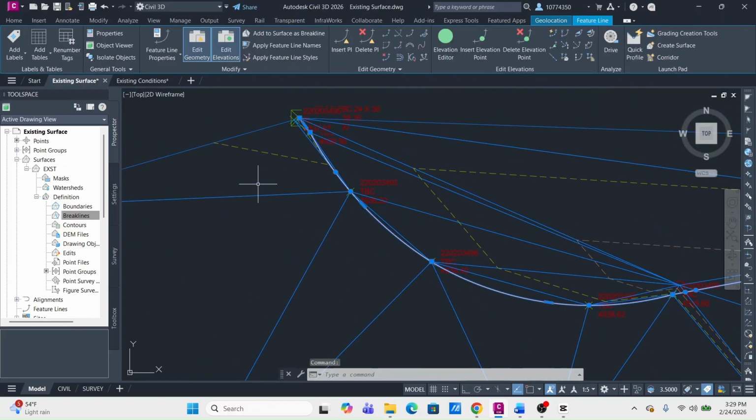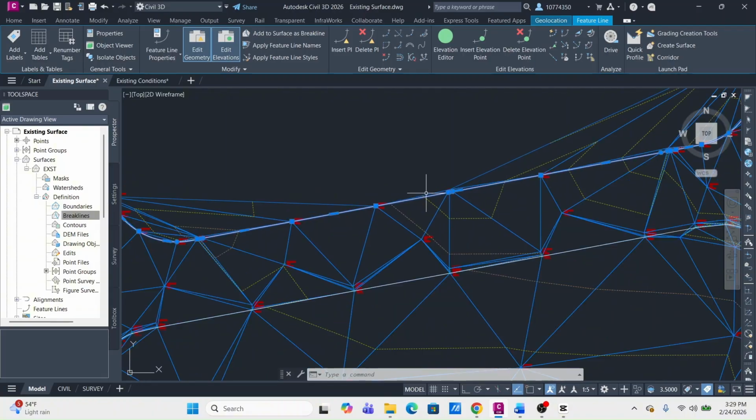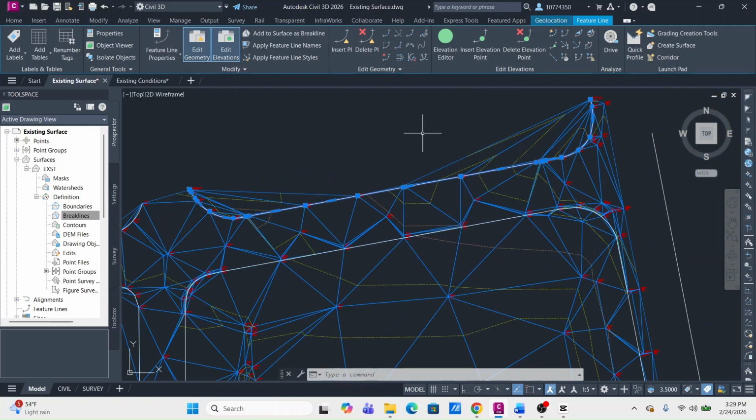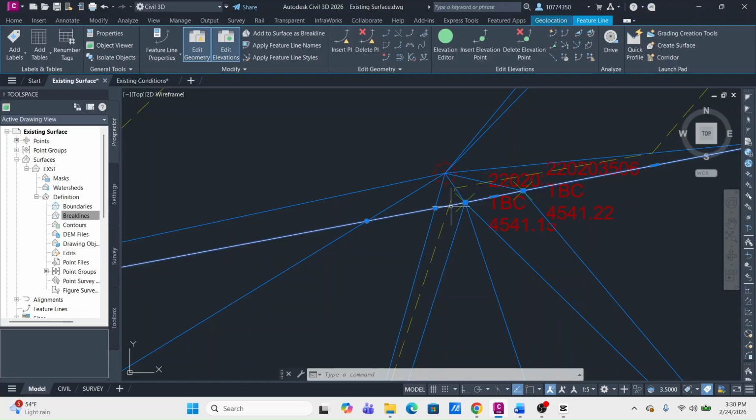So first off, let's click on this. This guy has its own ribbon with a whole bunch of different editing options and modifying options along the way. When I zoom into here, there are these boxes on your vertexes, and then there are circles along here which are inserted PI points, and your PI points are points of interest, and it'll make it so triangles will snap to it and so on.